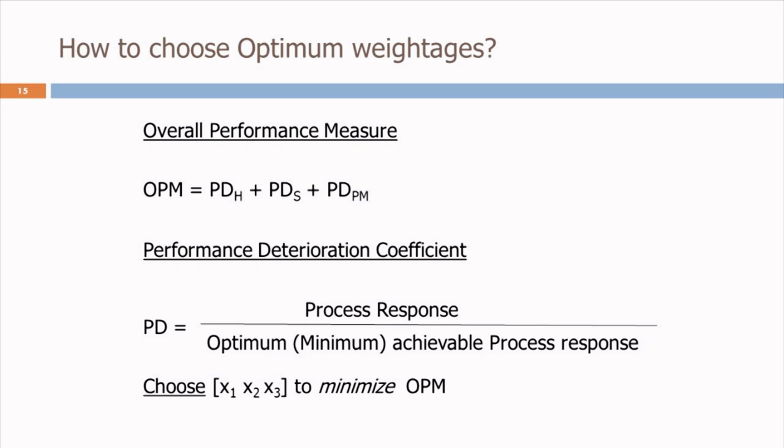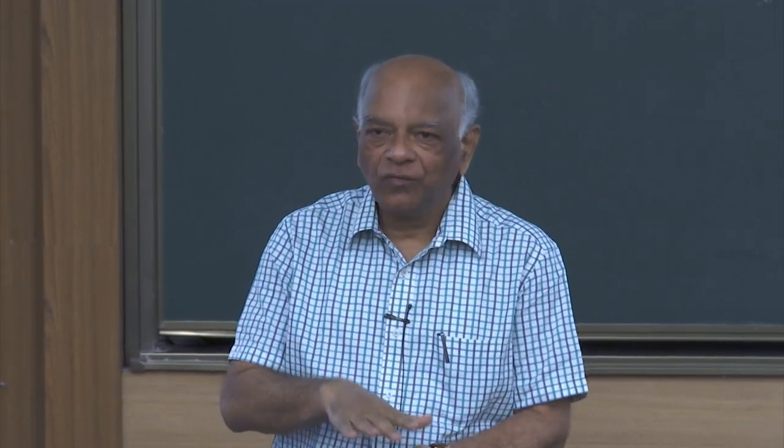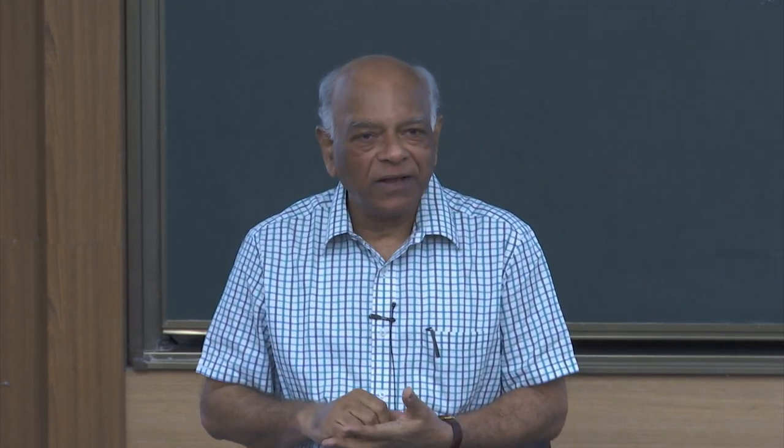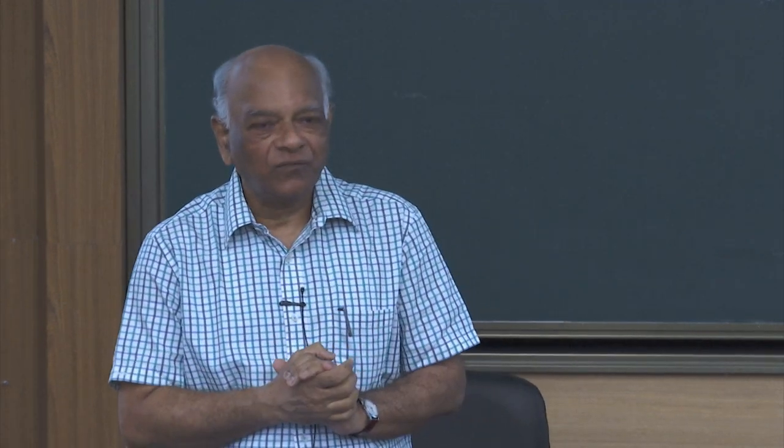So the whole algorithm works in this way. You propose this one, you minimize this, you go back into that, choosing this W1, W2, W3, and do the optimization to calculate theta x, theta y. So there is a double layer of optimization, and finally it comes out with the oriented model. It has slicing, it has all the types of contours for each layer, it has toolpath planning, and that can essentially be passed on to the machine for the purpose of fabrication.